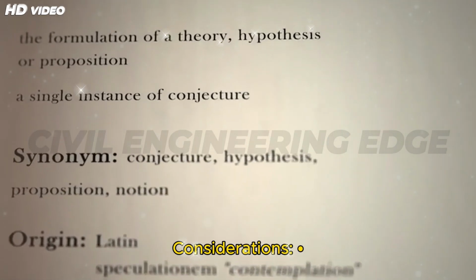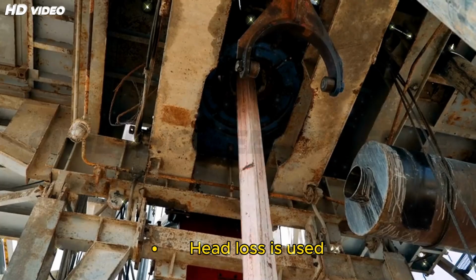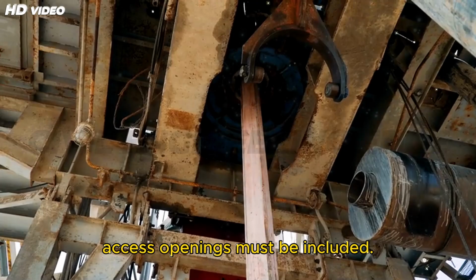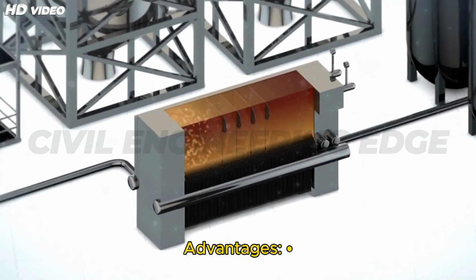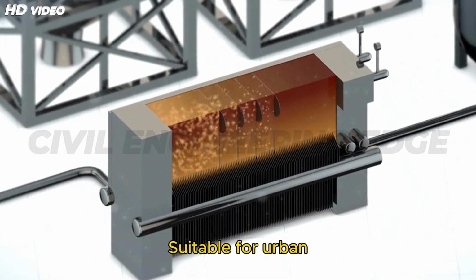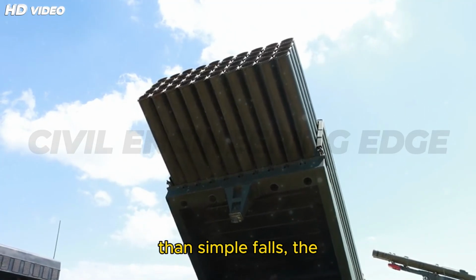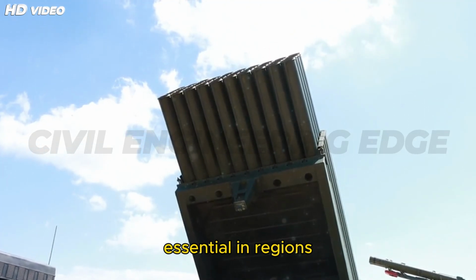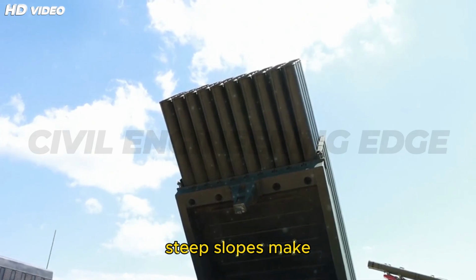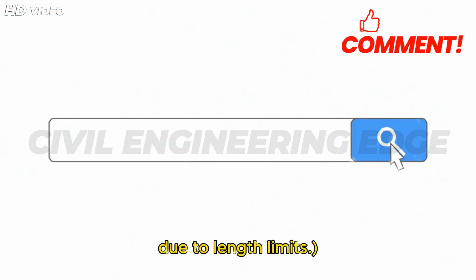Hydraulic considerations: energy loss is calculated by Bernoulli's equation. Head loss is used to estimate the height of the well. Adequate freeboard and access openings must be included. Advantages: highly compact design, excellent energy dissipation, suitable for urban areas and sharp terrain drops. Though costlier than simple falls, the siphon well drop is essential in regions like Maharashtra's Western Ghats, where steep slopes make horizontal structures impractical.